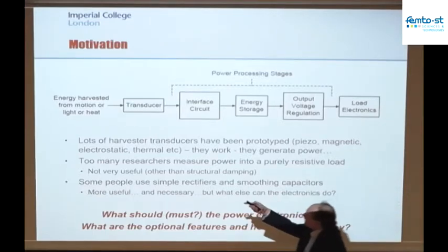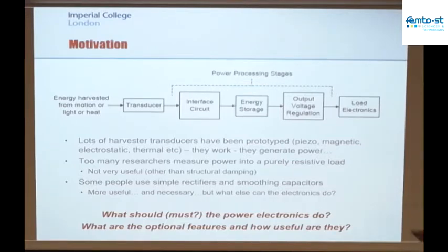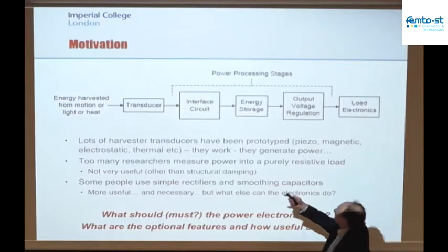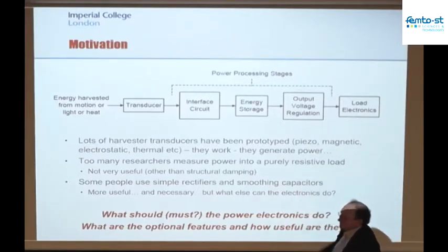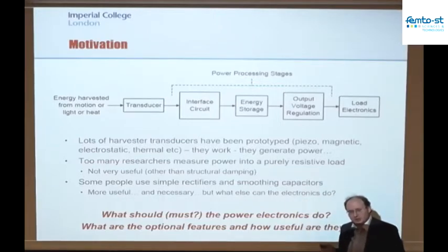Transducer. In our case, motion is going into this transducer. The transducer within this project is going to be piezoelectric, but it could potentially be the moving plate capacitor or the electromagnetic approach. There's an interface circuit, the first bit of our power electronics, which is going to get the energy into the energy storage unit, and therefore there are two roles that interface circuit has to play. It has to do rectification to get an AC into a DC energy storage, and it has to make sure that we get the right force on the transducer to maximize the power density.